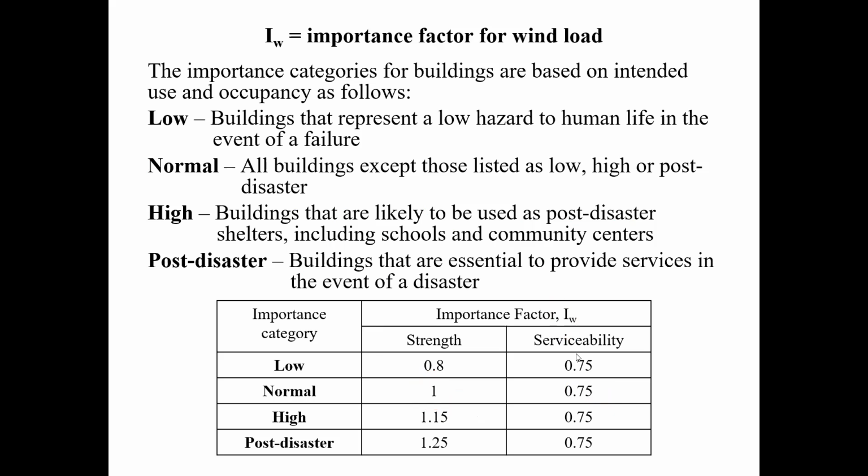So I have a quick question. Yes. So for serviceability, we have to recalculate all what we just did, but instead of using 1, you don't have to. That's what I'm saying. You're using 1, and then you know that mathematically for serviceability, your importance factor is 0.75. So you take your strength and you multiply by 0.75. Oh, okay, I get it now. Thank you. It's just math.